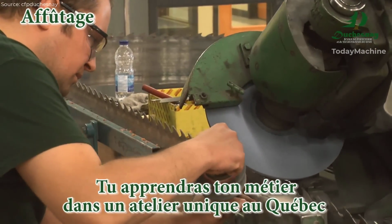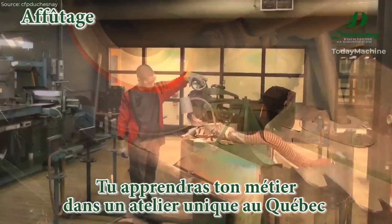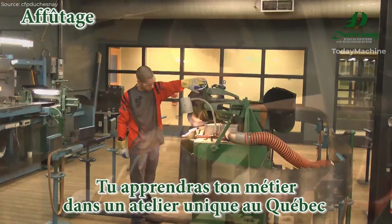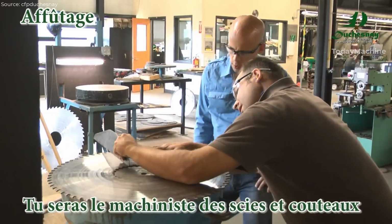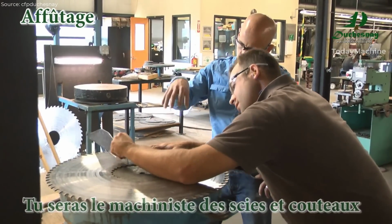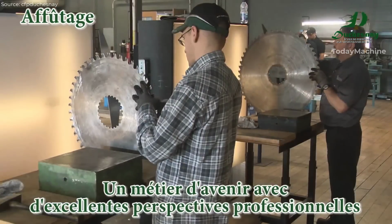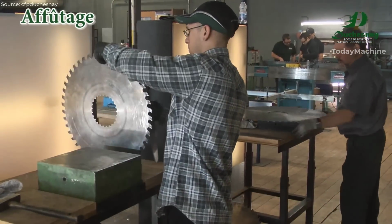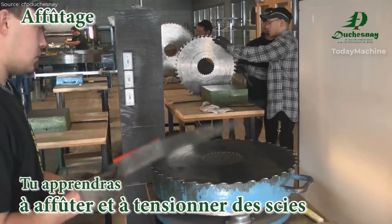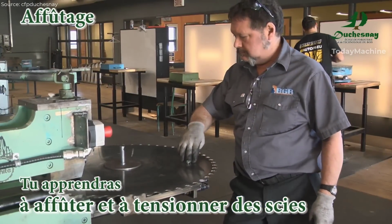Sharpening and tensioning saws. One of the most critical skills you will acquire is sharpening saws. This process involves using grinding machines to refine the cutting edges, ensuring that they are sharp enough to cut through materials efficiently. You will also learn how to tension saws, a technique used to ensure that the saw blade remains straight and does not bend or twist during use. Proper tensioning is vital for maintaining the accuracy and safety of the saw.